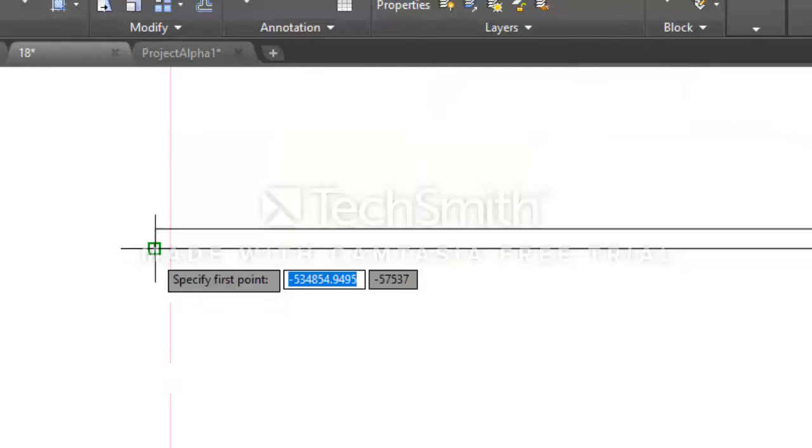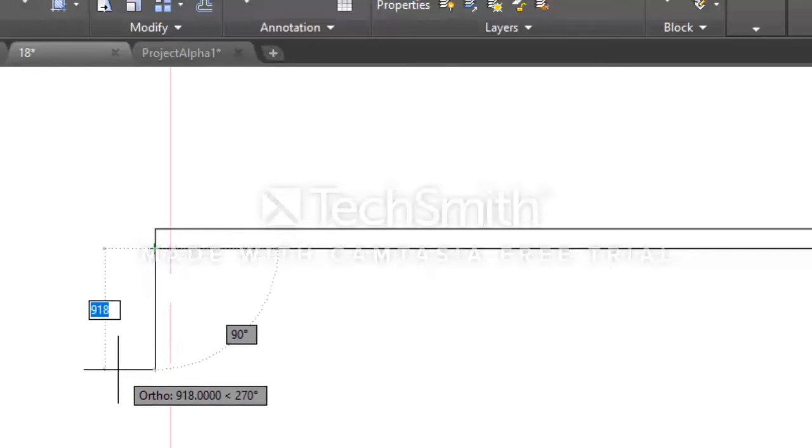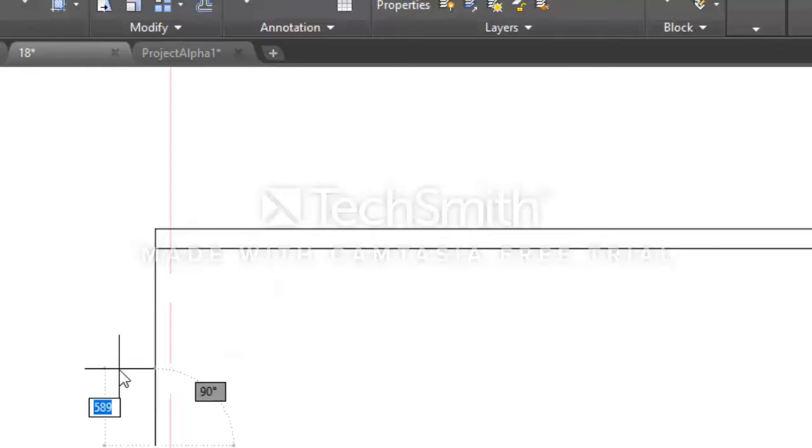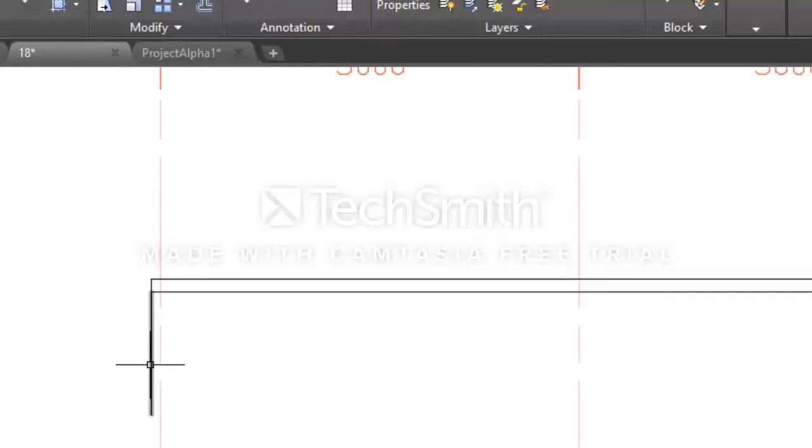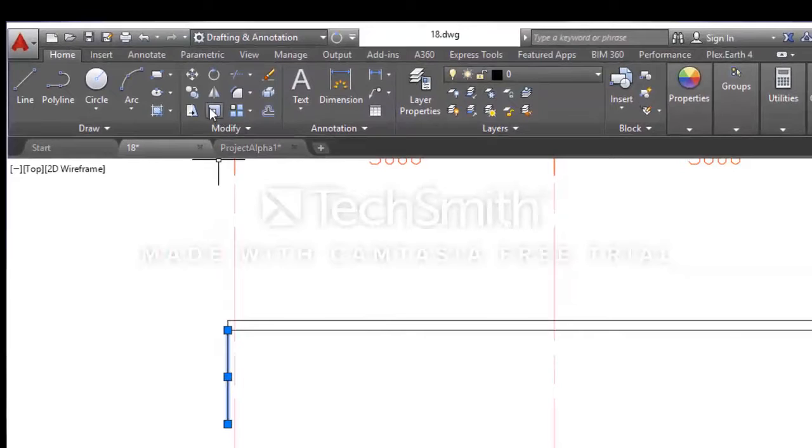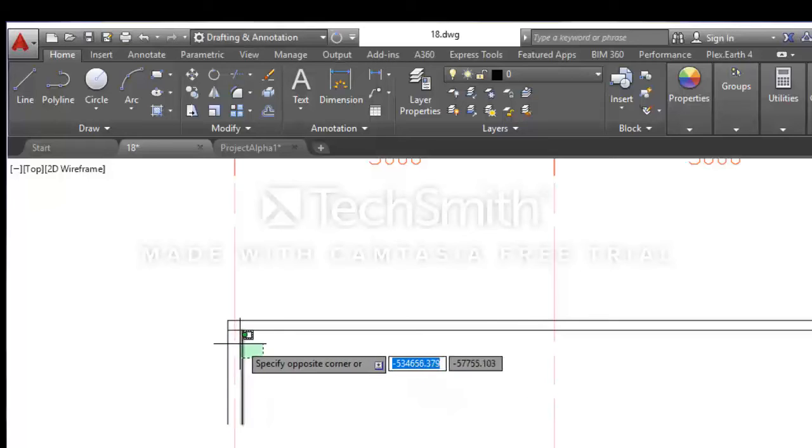So I've activated my line command. I'll draw a line downward from the bottom of the oversite concrete. So I'll enter 1,500. That is 1,500 mm, 1.5 meters. So this dimension, I'm going to copy it inward 230 mm because that is the width of my foundation wall. So what I'm going to do quickly, I'm going to select the two. Okay, before doing that,